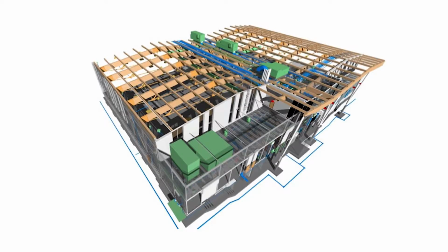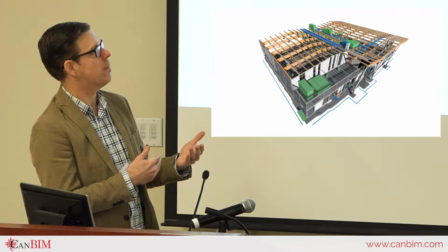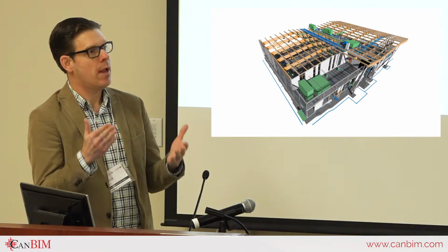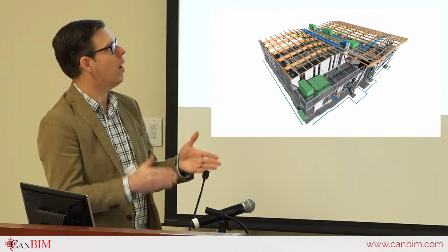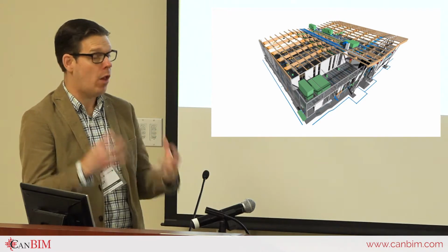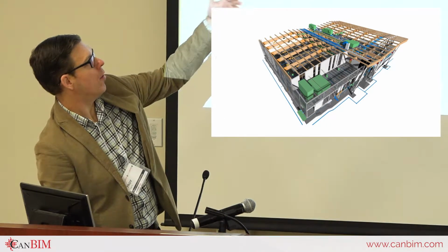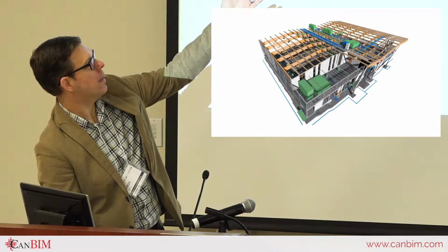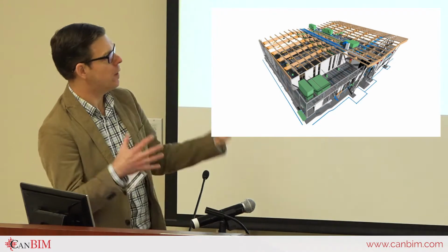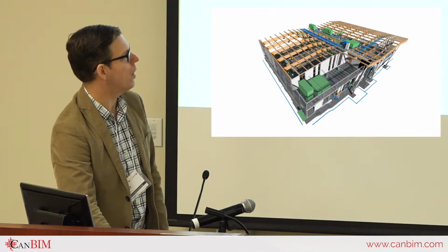We were talking about color and different things like that earlier. One of the things we really did on this job was use Navisworks to create visualization for the design teams to try and look at those clash detections, the different scopes, to really help us all understand where those pieces are. We definitely used color a lot to make those things work. So you can see blue is all piping, green is HVAC, those kinds of things. So we can really see those components and where they were when you built.